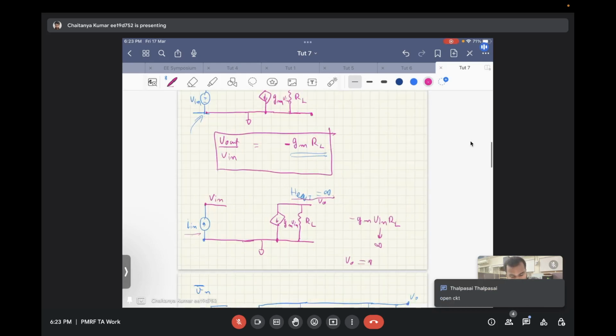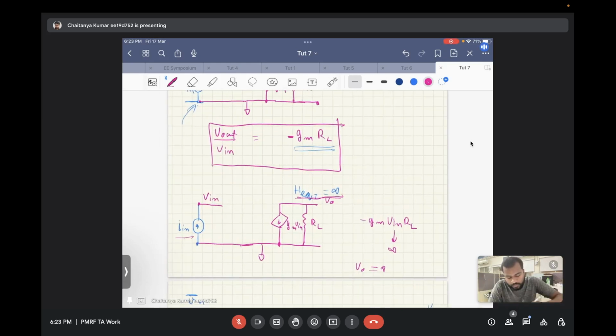Yeah, since it was open circuit, we found that the transfer function from input current to output is infinite. And to find the input current source, what we do is divide the whole thing by the transfer function squared. So we will be dividing the whole thing by infinity squared, so we get the input referred current noise source equal to 0.